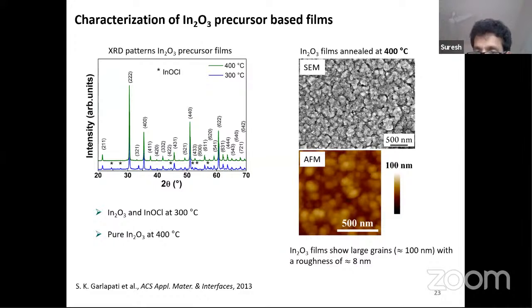These interacted electrons will be detected by the detector. So when the electrons interact, they carry the information or the morphology of the films or the particles. Backscattered electrons are nothing but elastic scattering electrons, whereas the secondary electrons are actually coming from the top surface, 5 to 50 nanometers of top surface.